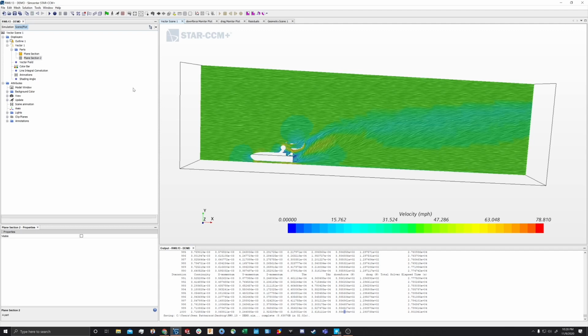And when you do that, you're gonna see either if you're doing it on this plane here that splits the body in half like this, you'll end up seeing how the flow is different across the span of the wing, or the wings that you're looking at. And if you do it on the other plane, you're just gonna see those vortices as they move backwards from the car. And to do that, you just go down here and click on the animation, and click discrete sweep.